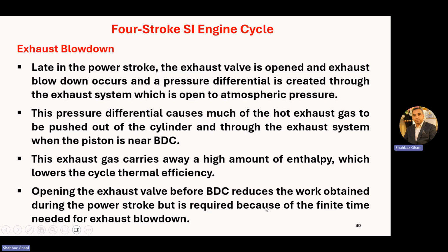but it is required because of the finite time needed for exhaust blowdown. And this exhaust blowdown is very, very important because when the piston is in the exhaust stroke, if your exhaust valve is not open and the piston reached BDC, it has to come back. Hot gases are there, high pressure is there, so it will require more force.